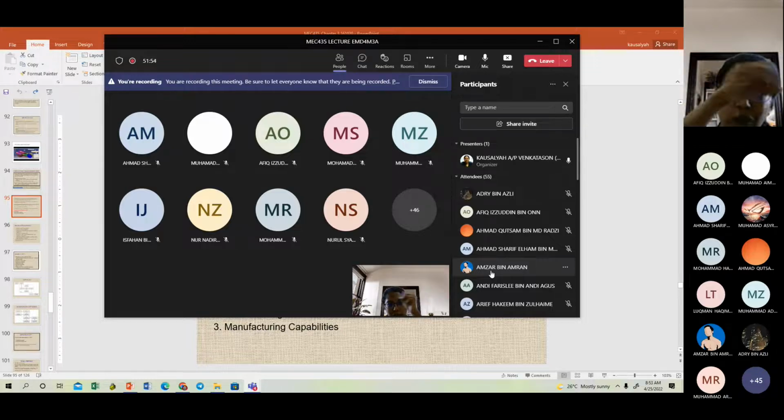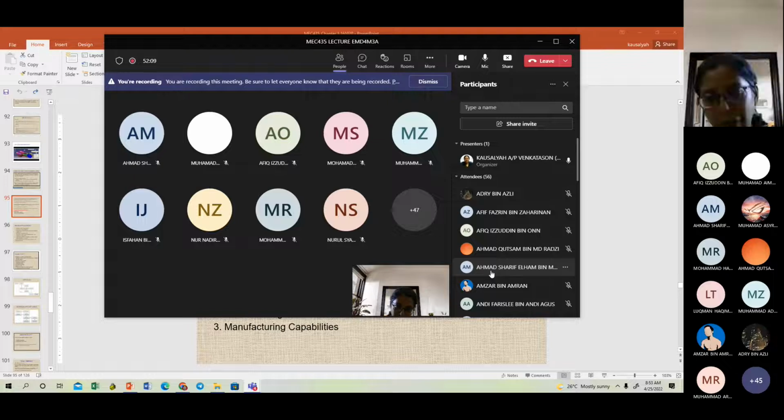that you're going to use, right? Let's say you're doing injection molding, you're generating the machining. So if you're doing your machining, you will see the machining simulation. If everything goes well and fine, you can click generate the NC codes. So your model is there, your analysis is done, your manufacturing simulation is done, and now you generate the cutting codes, the NC codes, and you just have to send it into your manufacturing machine. So if you notice, there is no, as per se, lab sheet or route sheet or standard operating procedure, because it's very much dependent on your CAD model.